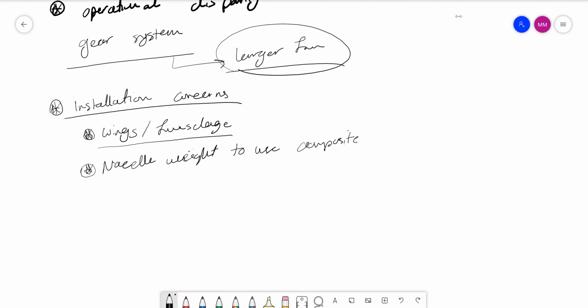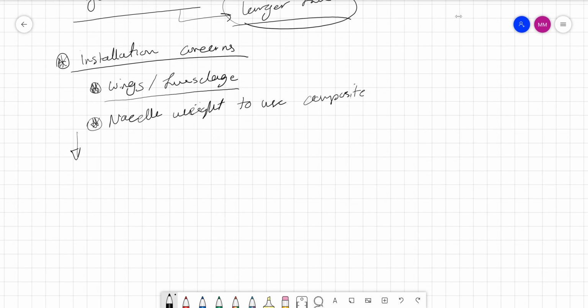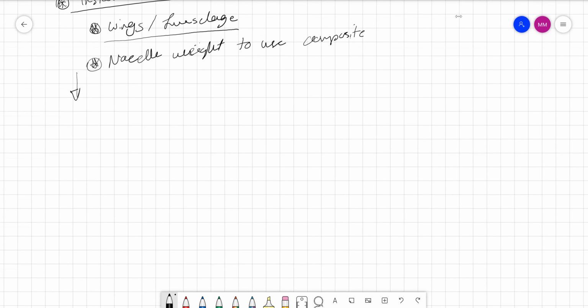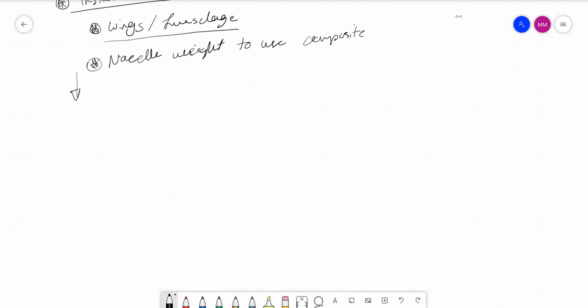Okay. There are a couple of other concerns that we don't want to get into. You're always welcome to read more about this. But I just want to introduce you to this new technology that's out there, the ultra high bypass turbofan engines. And the main concept, whenever you get a question that was talking about the ultra high bypass engines, your main concern is usually to calculate the TSFC and compare it to an older design and see how much of an improvement you will get.